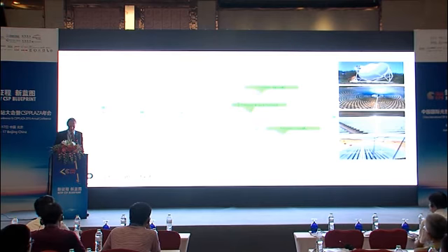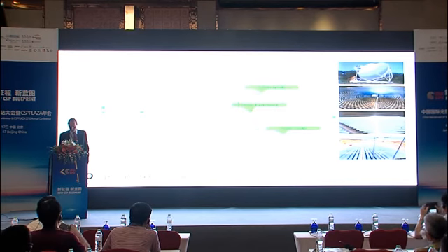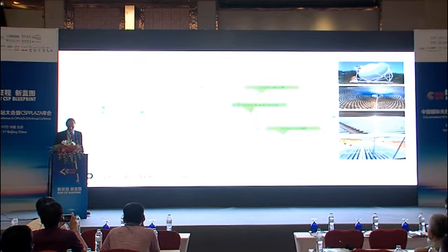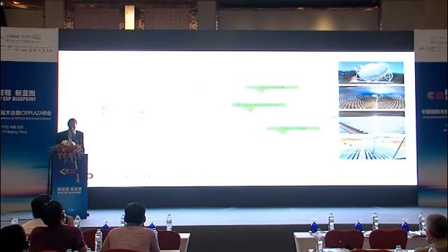You can see it in this plot. The plot is a little bit too busy, but please just look at the green lines. That's the efficiency of a heliostat by its position and the latitude, and you can see that here around the latitude of China, the heliostats in the north are very much more efficient, because of the cosine effect, than they are in the south. So that's why you always have asymmetric heliostat field layouts, because you can gain more energy out of the north field than you can out of the south field.